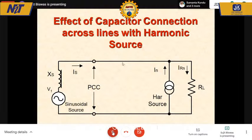And now I decide that I connect a capacitor across the line like this. This may be a physical capacitor for power factor correction. This may be a physical capacitor which I think of as a filter for my harmonic source. This may be an indirect capacitor coming from any one of the LC filters which I had tuned at a higher frequency, and at a lower harmonic frequency, this will appear as a capacitor. It will cater to all the conditions the moment I connect a capacitor. Either it is a direct capacitor physically, or it is a capacitor arising out of any filter connection. This is the network that I have created.